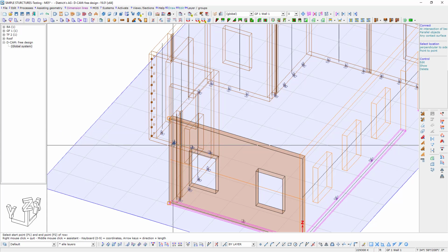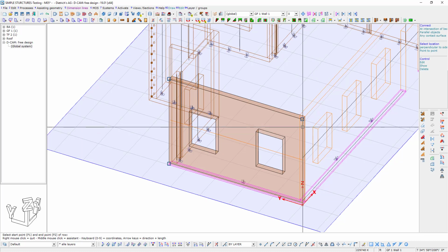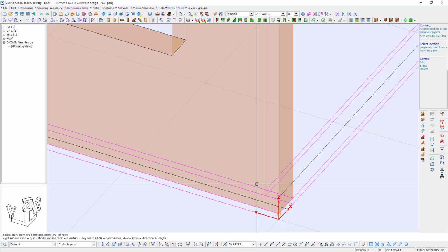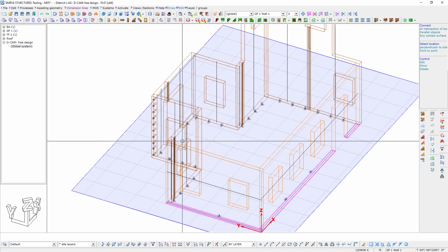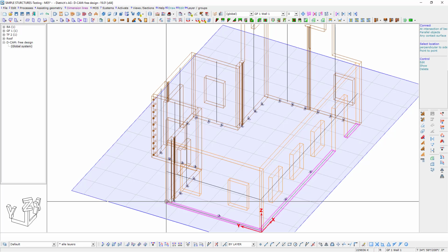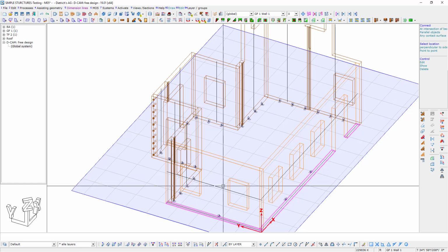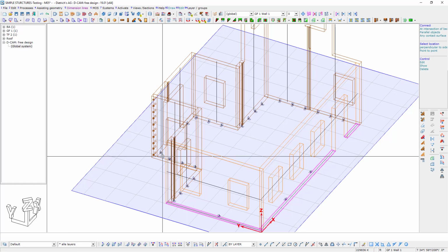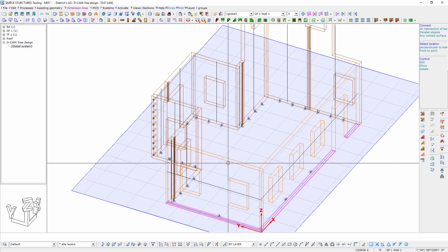We get that warning keeps popping up. Why is that? If I come to this edge, I'll have the same result. There we are, edge perpendicular to axis. So if you run into this, and you might wonder what's going on, on further analysis we'll notice the edge we chose is in fact perpendicular to that axis. So it's not going to apply those drillings. And I think these drillings are mainly meant for beam work, and the CLT panels are much different than beams.